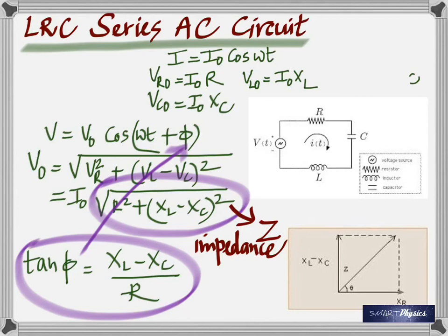And also when you consider that this is the square of that term, it doesn't matter if VC was bigger than VL. Why? But the most interesting thing is, what if both of them were equal? What if the voltage across the inductance is exactly equal to the voltage across the capacitance? Isn't that possible? If that takes place, then the resultant is just the voltage across the resistance, because the other two cancel themselves out.